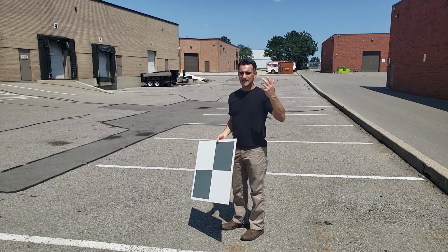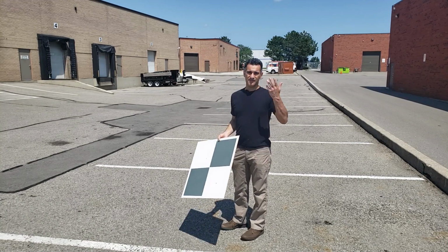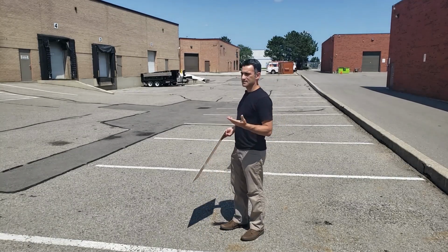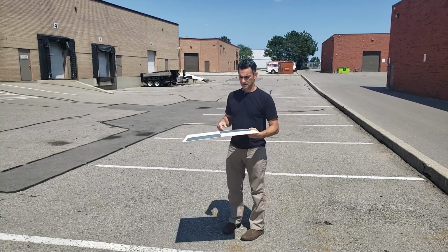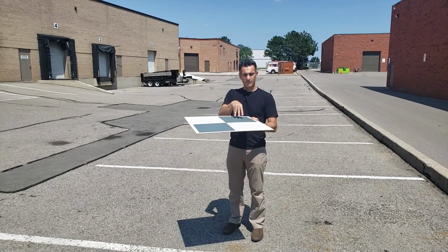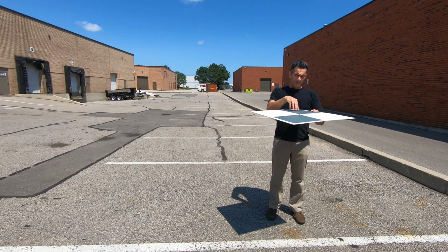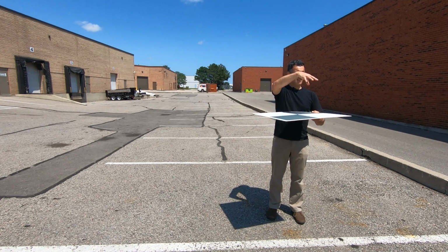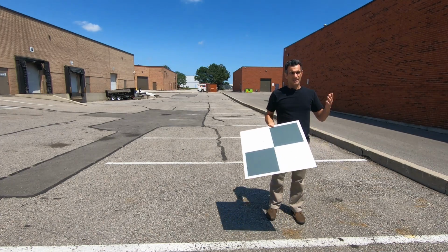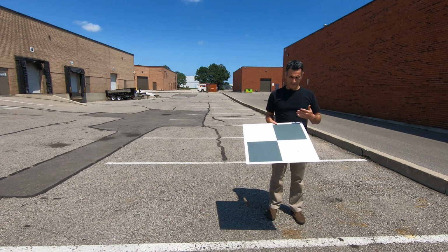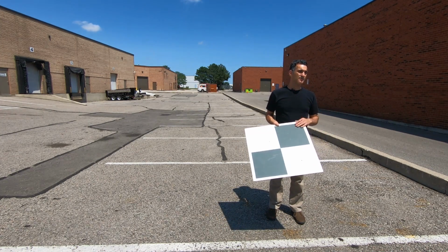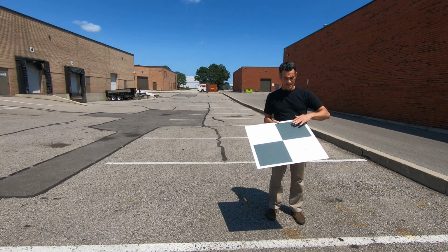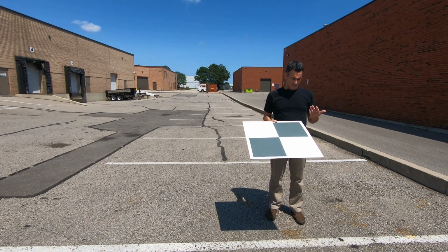I'm not going to go really high because over this small distance, if I get up to 90, 100 meters, then it's not going to take that many photos. As you can imagine, if you're really close to the ground, you have a small field of view, so you're going to be taking a lot more photographs, and as you get higher, you get a wider field of view, so you'll be taking fewer and fewer photographs. So that's one way to balance the efficiency when you're flying the drone, and to think about how high can I go to capture everything, and how close do I need to be